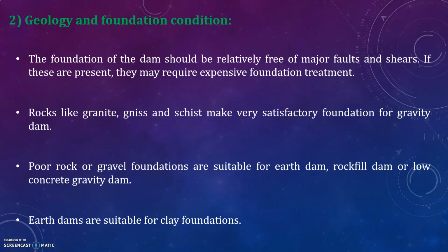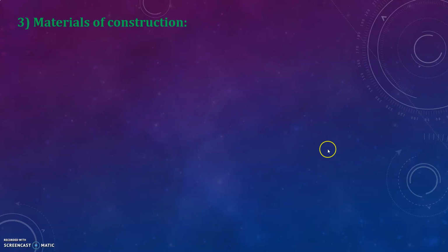Hence, such foundations are suitable only for either earth dam or low concrete gravity dam, but not rockfill dams. Clay foundations have often the problems of long range consolidation under the weight of the dam, resulting in cracks. Hence, only earth dams are suitable with proper foundation treatment. Gravity dams or rockfill dams are not suitable on clay foundations.